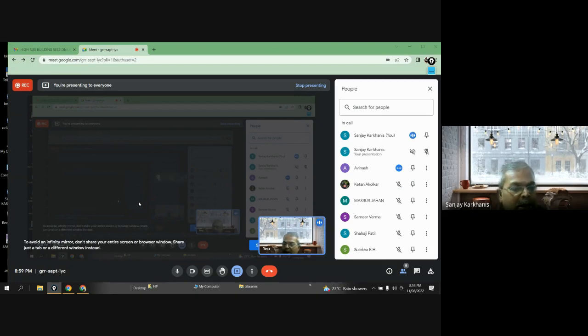See, actually, today I have brought some old file. Actually, that was not our file. I will check the file that we have created, that MDB file. Unfortunately, I might have chosen some older file, and that's why we were getting this, because I don't remember that we have the size 230 by 900 for the column. I think 230 by 530 and 230 by 450 was the size.